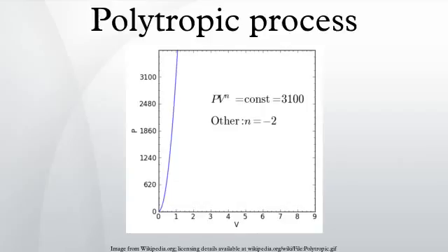Energy entering the system increases the energy of the system, and energy leaving the system decreases the energy of the system. The sign convention is that heat transfer into the system is positive. Work done by the system is also positive. With this sign convention, the heat transfer term is added to, and the work term is subtracted from, the internal energy change. Define the energy transfer ratio, K.